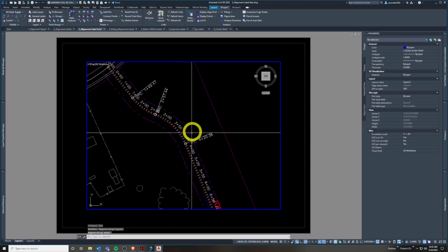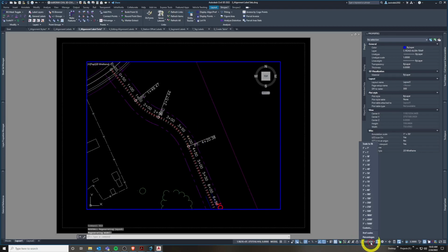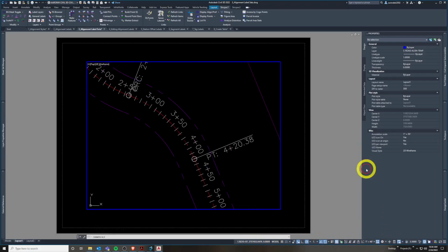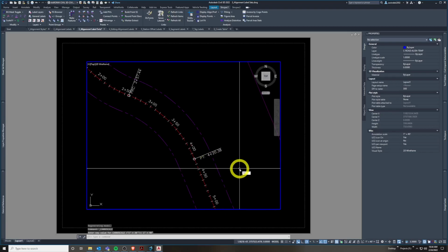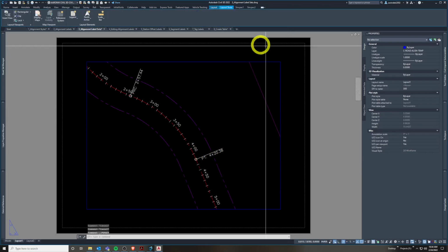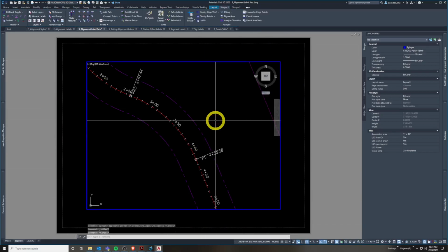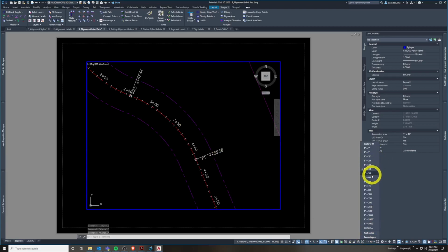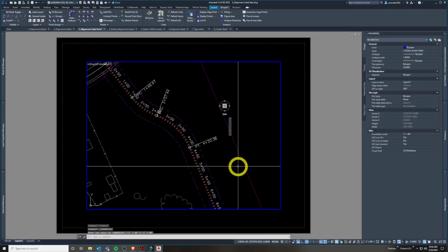And let's say that I'm in this viewport. Let's put it at, here's your scale here on your toolbar gizmos and stuff. I'm going to say 1 to 40 scale. And it should have regenerated automatically. Here's what it would look like if I plotted. I don't have a title block and fancy stuff here, but these will update if I go to 1 to 80 scale.